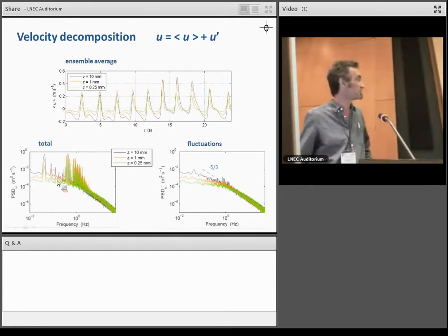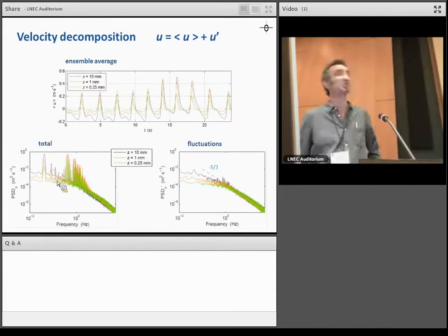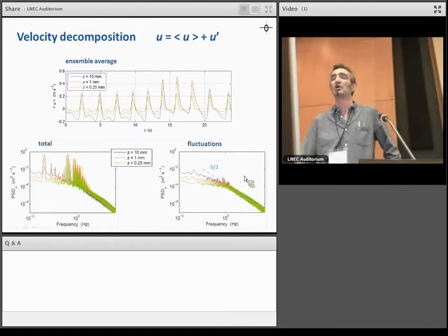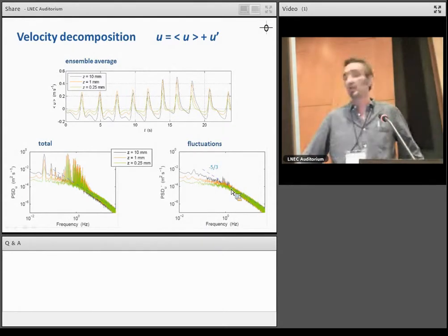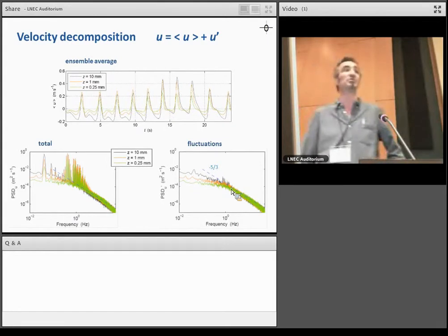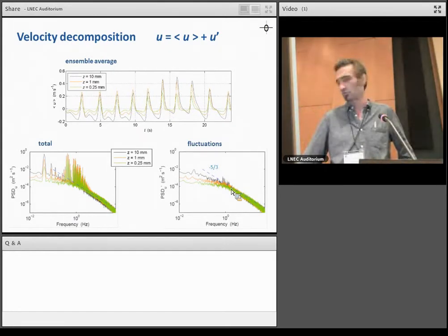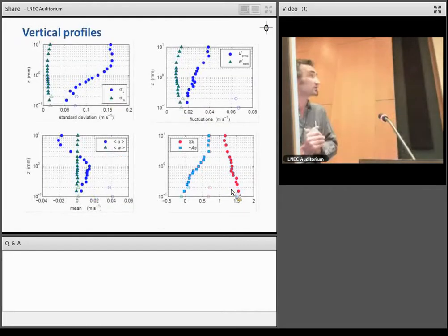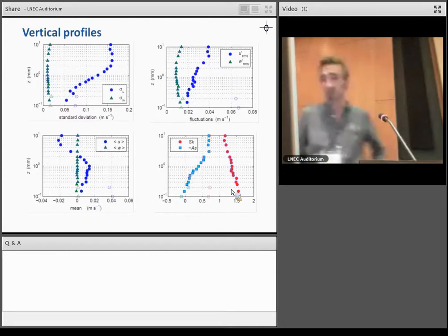On the left, that's the standard deviation where we can recognize a low trend. On the bottom, or very close to the bottom, we may be influenced by local roughness due to the sand grains that constitute the concrete bed. On the right, those are the fluctuations. You may note that it's almost uniform for the vertical fluctuations, while the horizontal fluctuations tend to decay towards the